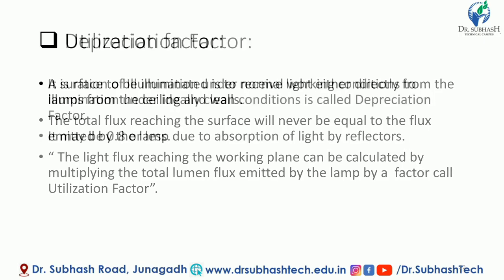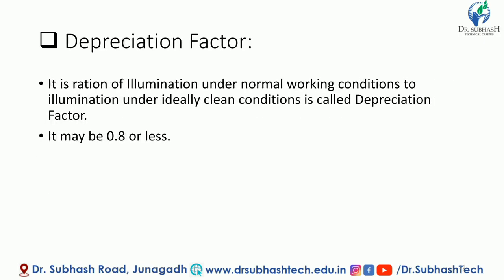So next, depreciation factor. It is the ratio of illumination under the normal working condition to the illumination under the ideally clean condition. Its value may be 0.8 or less than 0.8.